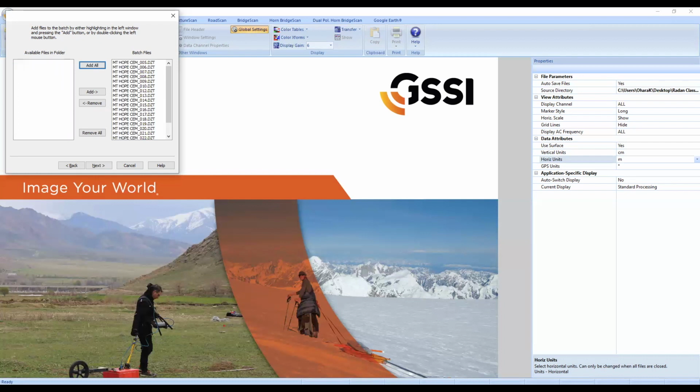If you had opened up the grid parameters PDF, you'll see that all of these profiles moved in the same direction. So this is another unidirectional 3D grid. For this reason, the order here does matter. Now, fortunately, it should already be in the correct order. You want to make sure your files are in ascending order. File 5 was the first one, and file 24 was the last one. So just make sure that this is, in fact, in ascending order, and it is, so we can hit next.